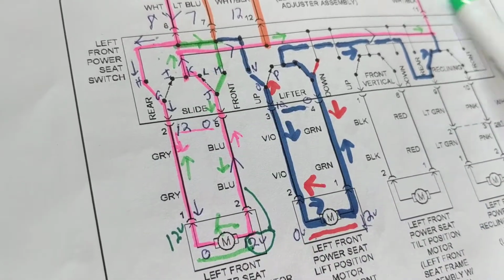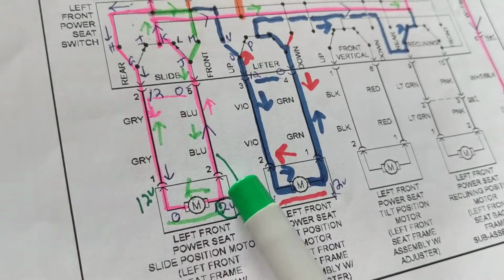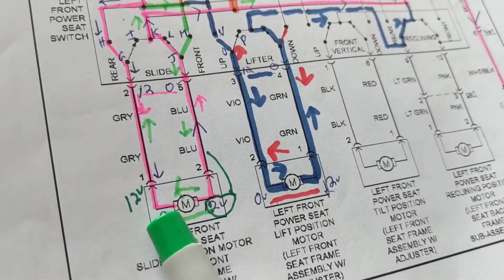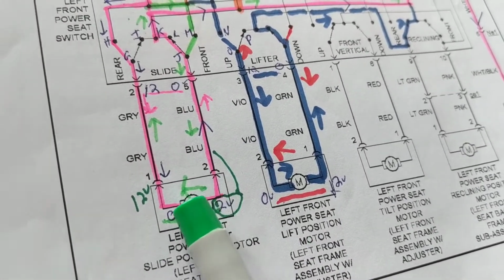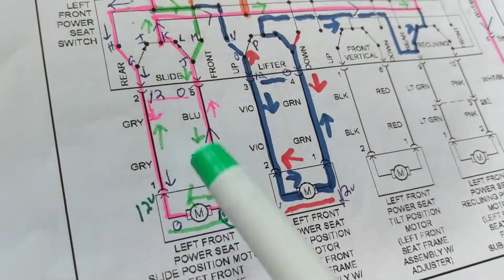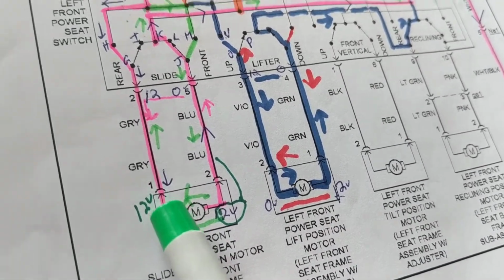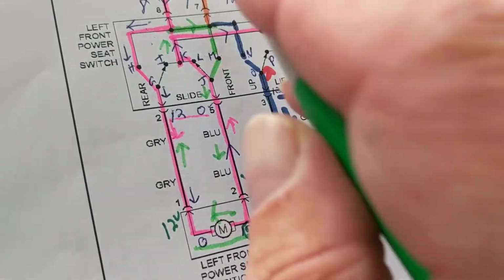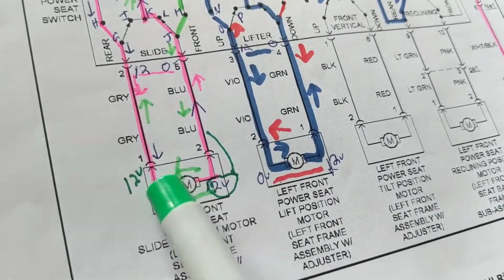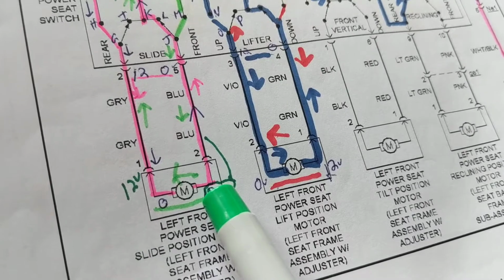The seat switch is over here. And you do it by measuring 12 volts. I put the meter over here, at the motor. If I don't get 12 volts going with the switch back and forth, it could be the switch, but also it could be a wire. But also, if I don't get 12 volts over here, something is wrong with the switches or the fuse. If I get 12 volts in either position, and the motor is turning, I know I have 12 volts in the motor.